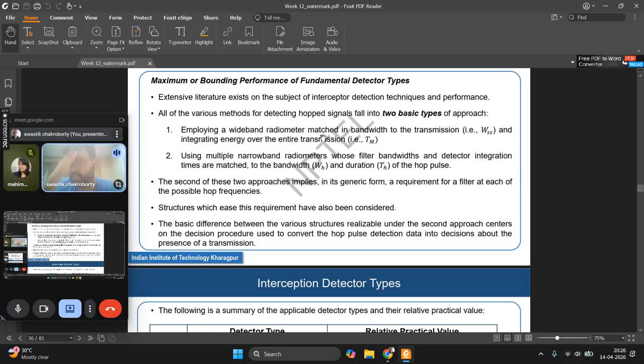The second one is of course better suited, but it is not always easy to implement, because you have to know the exact spread spectrum configuration, which is much tougher to know than the entire bandwidth. Usually the entire bandwidth reserved is pretty well known, and the military is bound to transmitting in that bandwidth, because their devices are designed as such and they cannot suddenly switch over to civilian frequencies.